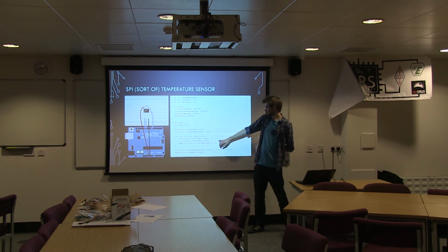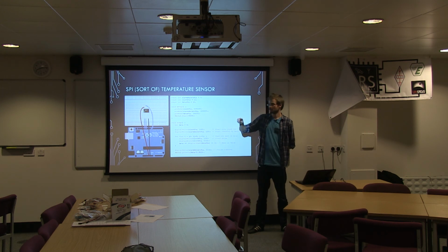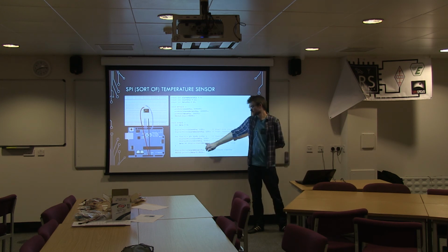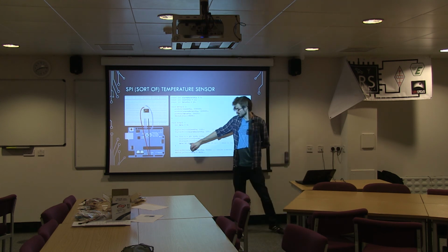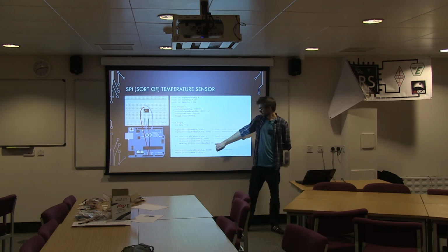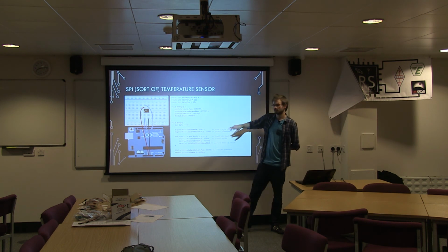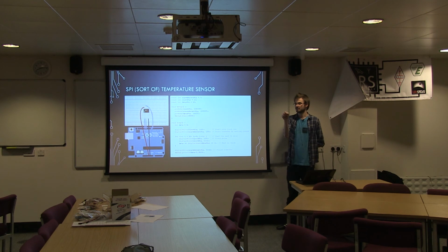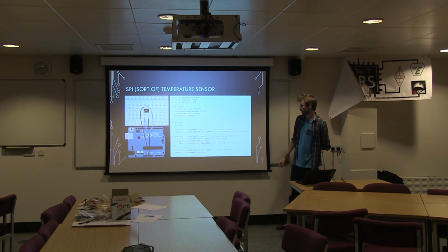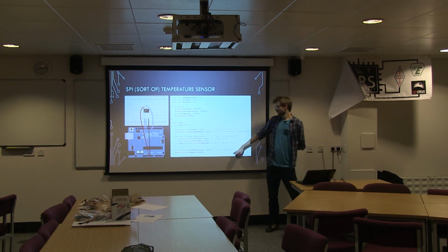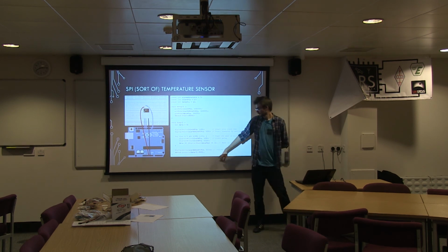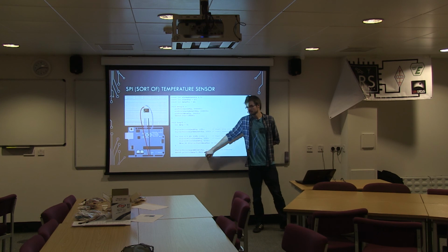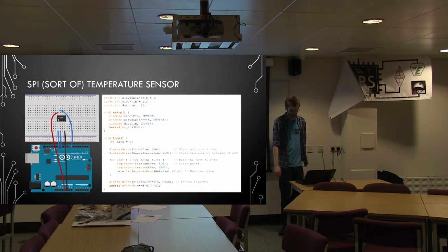We set the clock pin low and high, which gives it the rising edge it needs, and then we read in the data off our data pin and store it into our data variable. This double shift is bit shifting the data we're receiving into the next bit along every time we read one. Once we finish the transfer, we turn off the chip select line and then print it to the output like we were doing before.